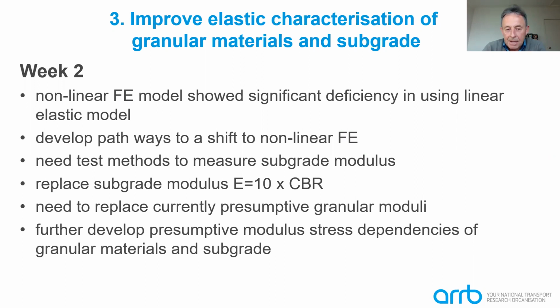Subgrade modulus has a major influence on designs, and we currently use this very simplified approach, 10 times the CBR. There are various empirical rules like this used throughout the world. There's a need to replace that and develop a process for design moduli that reflects the stresses in trial pavement configurations that are applied to the subgrade.